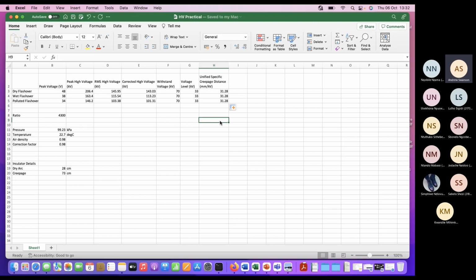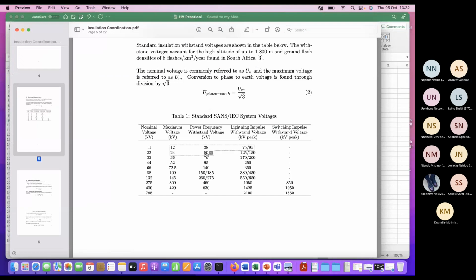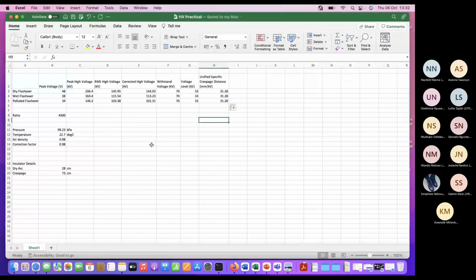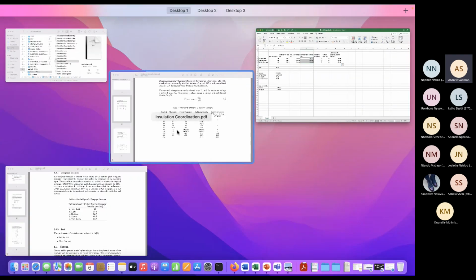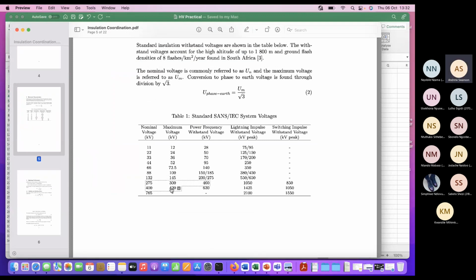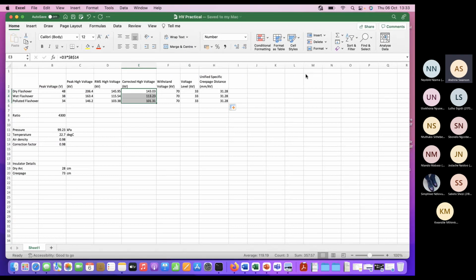Okay. I would have also accepted a 22 kV. 44 kV, we don't see that much of it. It might have been a bit out. All right. So that's how you're meant to determine the voltage rating. I got some great voltage ratings. I had flashover voltages of 143 and voltage ratings of 420, 150, 185. So it was very confusing to see a bit of that.